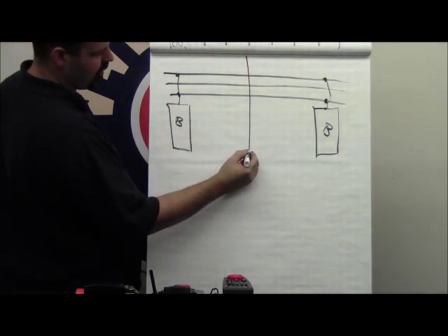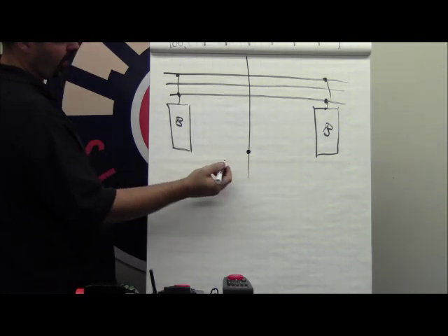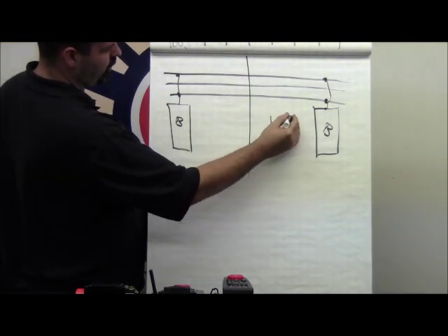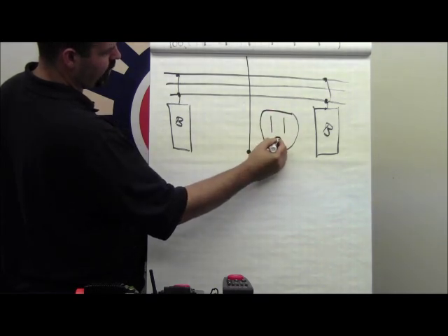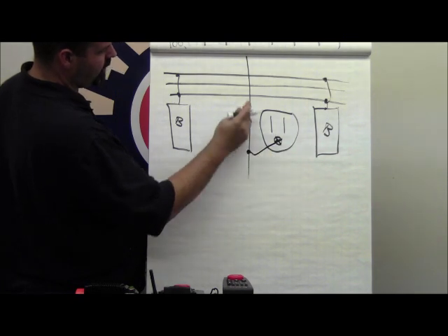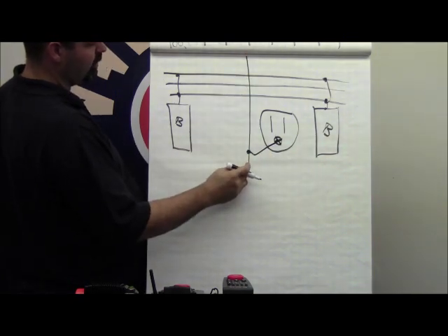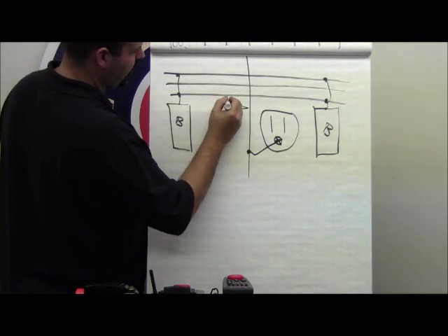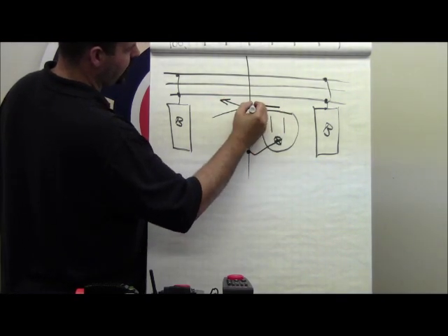That piece of conductive metal gets connected to earth ground. And all earth ground is that third prong on your electrical outlet. This one here. Earth ground tied to this metal shield effectively stops all of this signal and kicks it back.